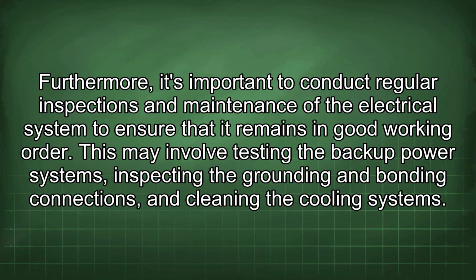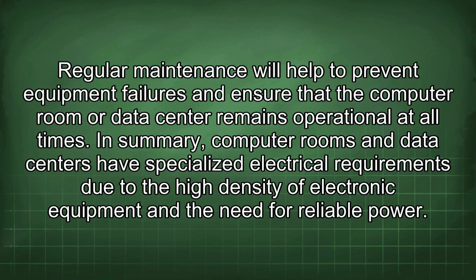Furthermore, it's important to conduct regular inspections and maintenance of the electrical system to ensure that it remains in good working order. This may involve testing the backup power systems, inspecting the grounding and bonding connections, and cleaning the cooling systems. Regular maintenance will help to prevent equipment failures and ensure that the computer room or data center remains operational at all times.